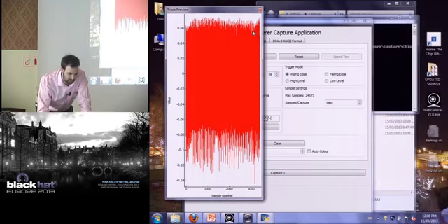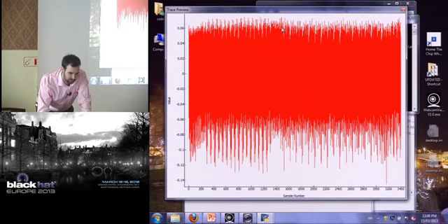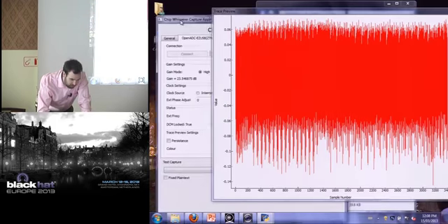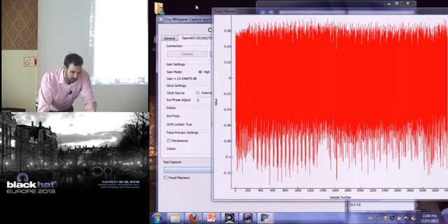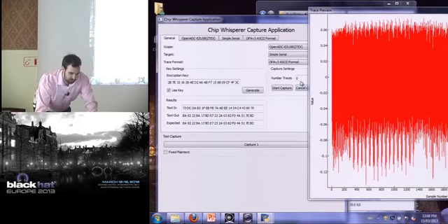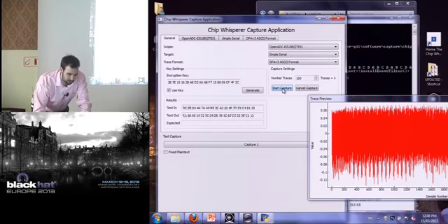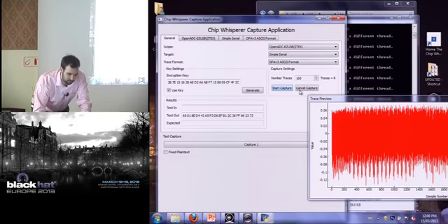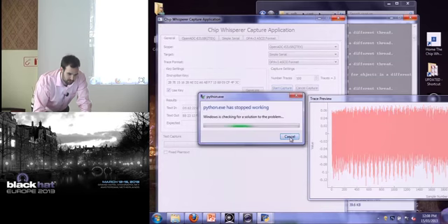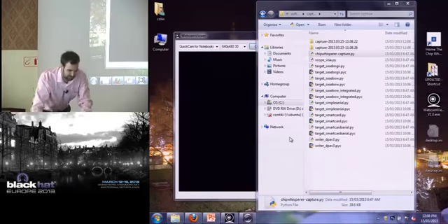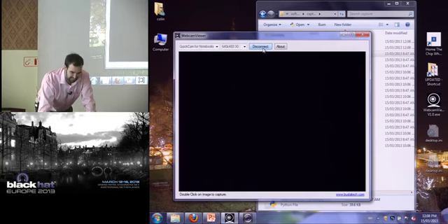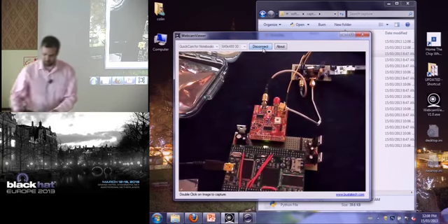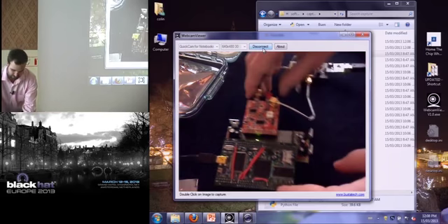So this is starting to look a little like what I showed before. This is a repetitive system. We can see that as I'm sending different data, it's changing a little bit. And now all I'm going to do is capture a bunch of traces. Say I want 100 traces. And just hit Start Capture. Sometimes you have to try it a few times, or it crashes. The USB cables I brought have broken in my bag a bit, so it's giving me some issues here. So I'm just going to use the pre-captured ones for now. It does normally work pretty well.